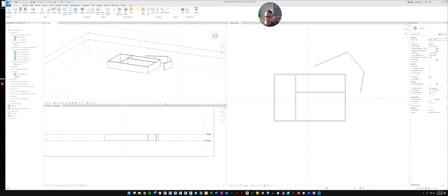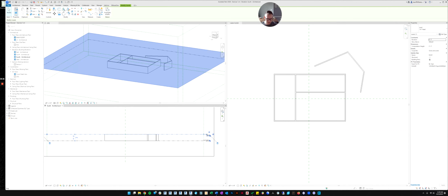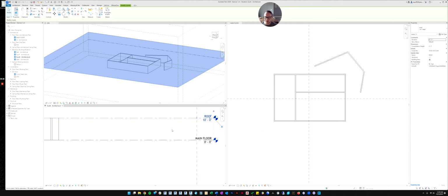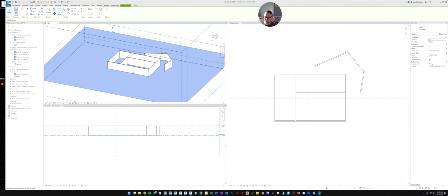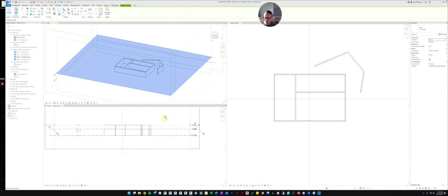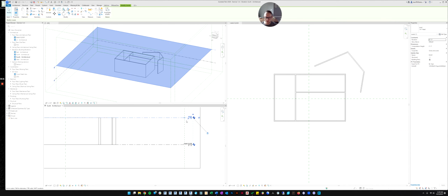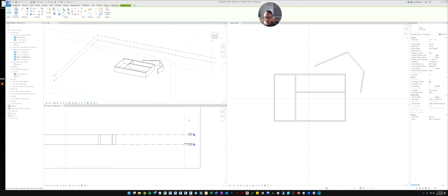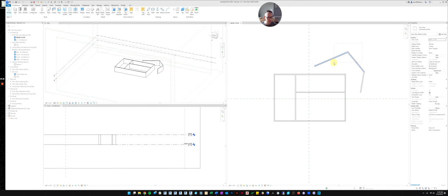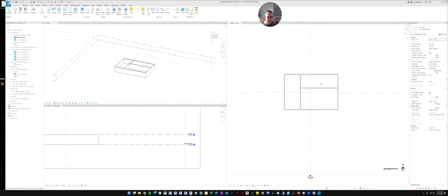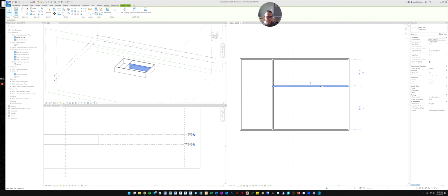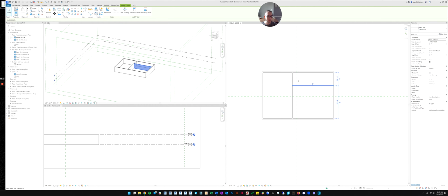See how everything now is aligned? And now I can change this to 10 feet, and all of the walls move up. I can also just drag this. You see how they just follow along? Okay, so let's put this back at 9 feet. Let's get rid of the walls we didn't want. All right, so now we have our little house. Let's call this the living room, the bedroom, and well, that'll be the bathroom.